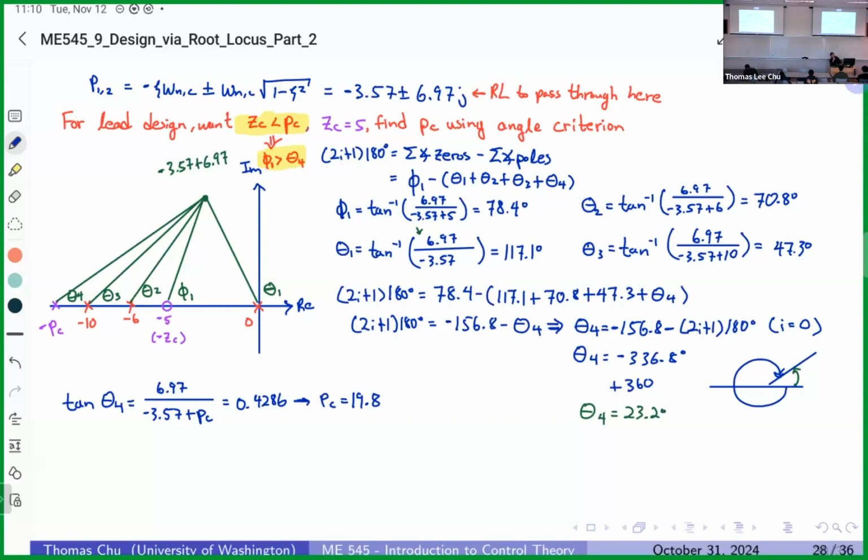I see it as, okay, maybe adding poles, you're increasing, well, that's not physical, but it's all code based for me. So when I increase the number of poles, I'm increasing the resolution of my transfer function. If I have a higher order system, I have more poles, which can represent more individual state variables. And maybe one state variable is going to be on the dynamics of a certain part, or maybe 5 state variables will represent the dynamics of, like, I don't know, a flexible arm.